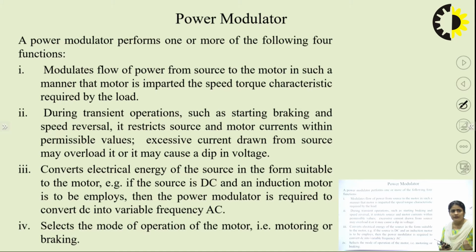And also it converts the electrical energy of the source into a form suitable to the motor, as I said earlier, depending upon the availability of the source and depending upon which kind of motor you are using to drive the particular load. Suppose I just take an example of electric drive. An electric vehicle is generally driven with the help of a BLDC motor, the brushless DC motor. The BLDC motor input requires a DC voltage, so the power modulator must be a DC to DC converter or AC to DC converter.